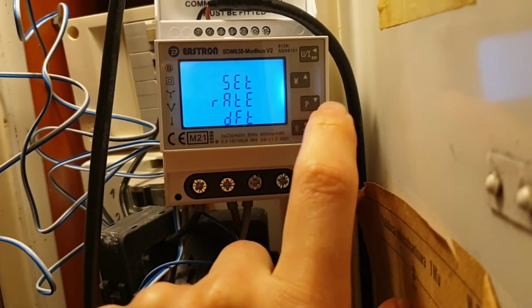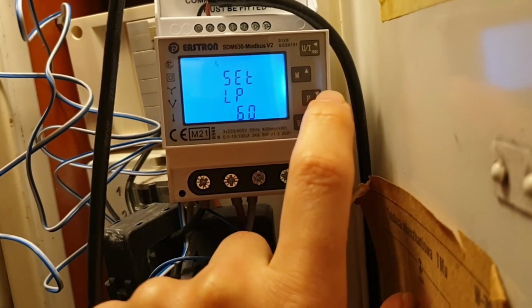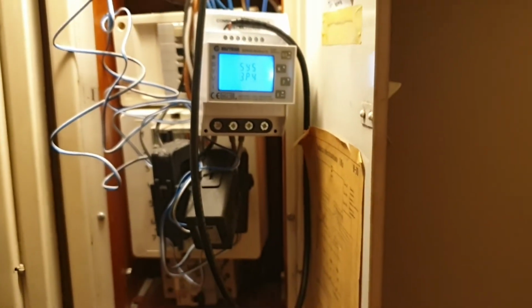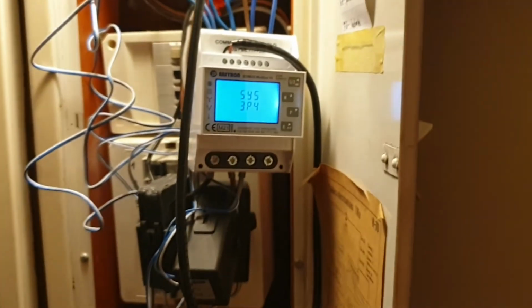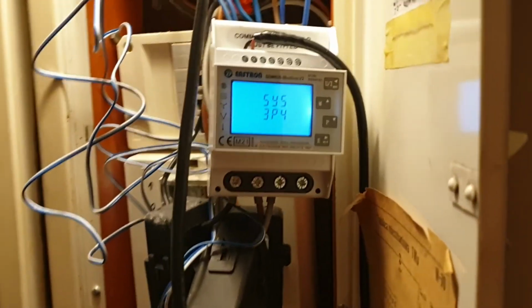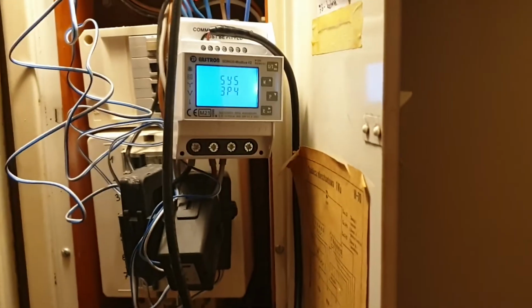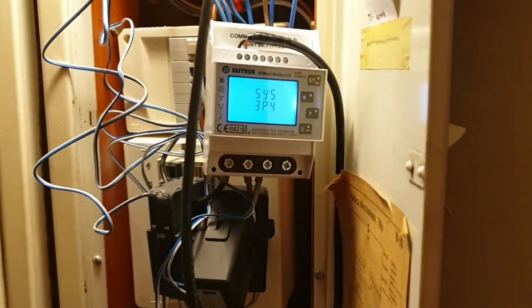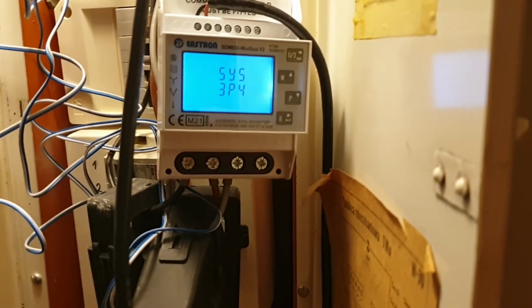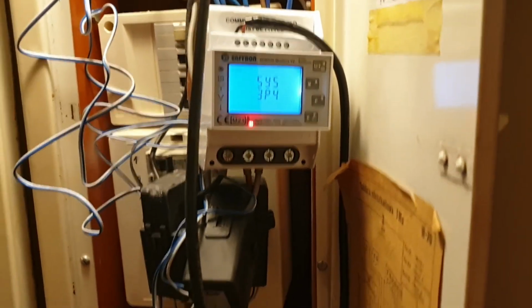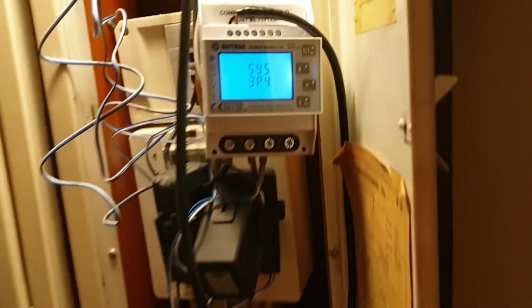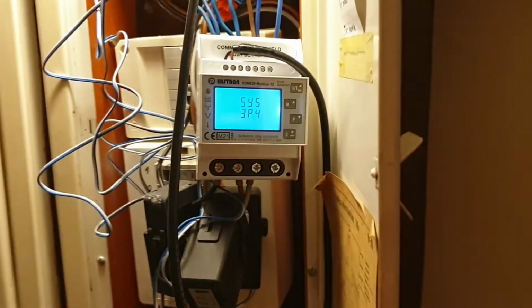So the transmission parameters need to be the same because we are using the parallel setup. So we have the inverter and that power meter connected in parallel to that Modbus to Wi-Fi adapter. Of course, we can also use the Modbus to USB adapter. I've already showed you that in my previous videos also. So here you have the configuration. P4 means 4 wires, and you can also change it to, for example, P3, P1, and so on.